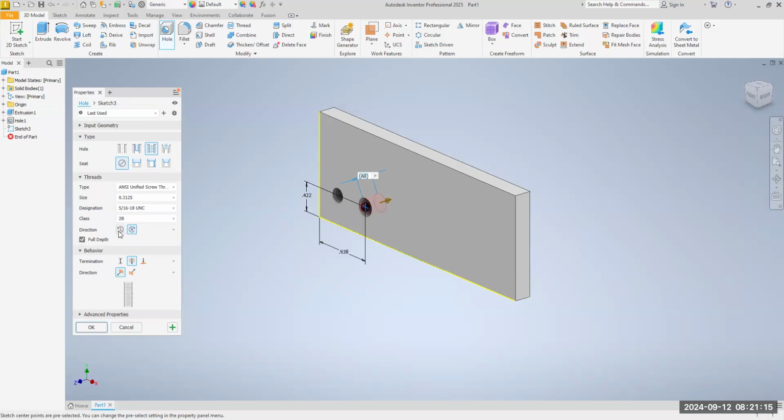By the way, we didn't talk about direction last time. Right is always the default, right-hand threads. When you turn a screw into a hole or into a nut, you turn it clockwise because that's a right-hand thread. But they have some screws you have to turn counterclockwise. That's a left hand. Those are oddball threads. Turnbuckles come to mind, where you have a right-hand and a left-hand thread. All right. So I'm going to say okie dokie here.